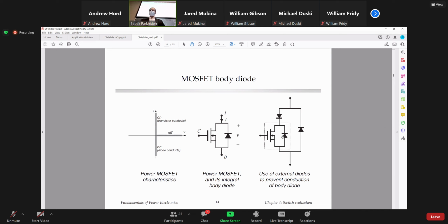In order to make it a bidirectional current, because now you don't want your MOSFET operating in reverse, you need this anti-parallel diode. This anti-parallel diode should withstand the voltage from top to bottom. So if you pick a 100-volt MOSFET, this diode is a 100-volt diode.